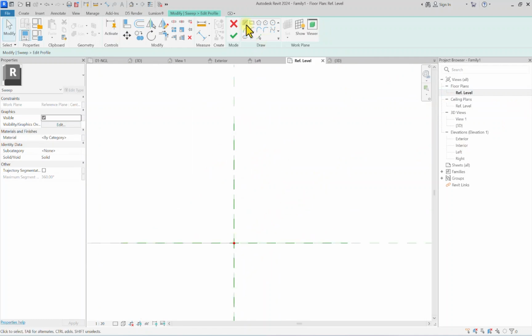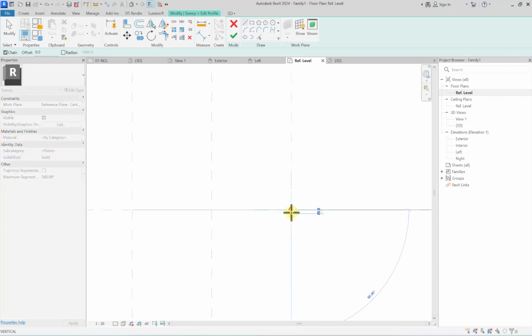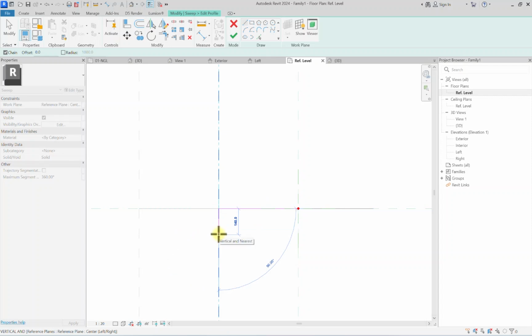If you want to see things closely, we'll click on one of these lines too. You can click on TL to turn off these thick lines. Then we're just going to sketch from this point inward. So we're going to draw a line to this center here. And we're going to draw another line offsetting, I think, 75 millimeters.